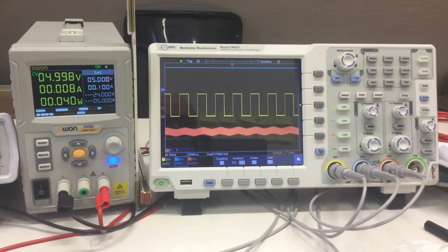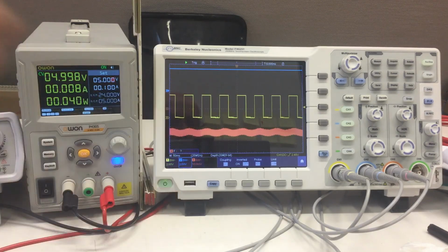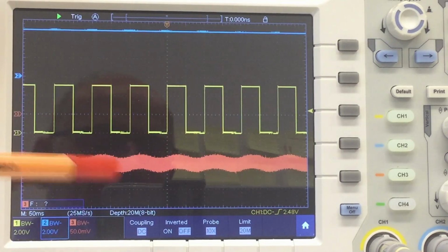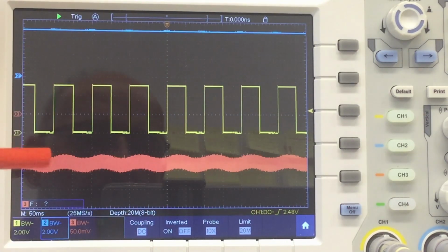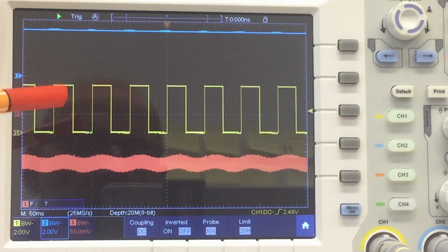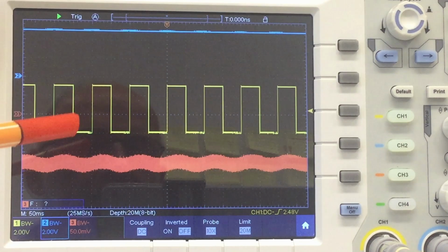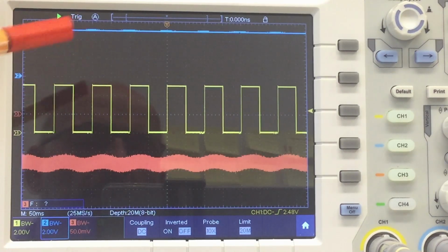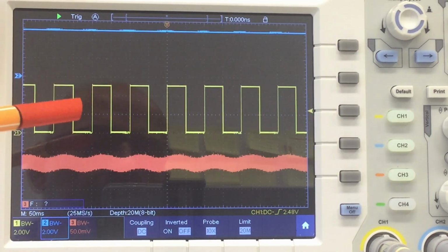And I will now, I guess, just focus on the scope. I'm feeding into the intermediate frequency input a 10 Hz sine wave, 10 millivolts amplitude with a little DC offset of 125 millivolts. Yeah, also a little bit noisy, like we would get it from the HB100 module. And out we get a 5 volt square wave with exactly the same frequency. Isn't that nice? And the voltage output gives us currently about 5 volts. So that would be the maximum signal level.